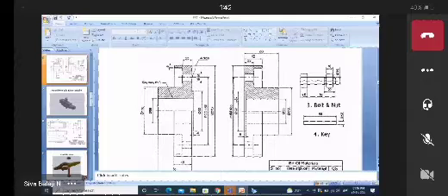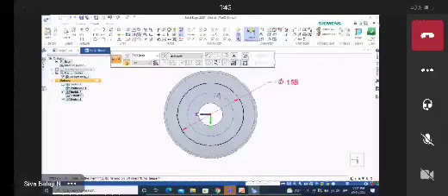Okay, if we did not mention in the plan, you have to consider the PCD as 158 mm, because in assembly you have to match those holes. Otherwise, in assembly it will not match the holes. Now you can convert this circle into reference circle.